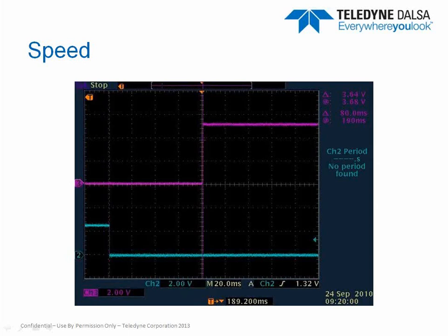And it was really constant. If you see the number below, it was around 189 milliseconds. So again, some of the vision software tells you the processing time, the acquisition time, but if you scope from trigger to output, you get the real true time for it. So do tests, especially again, in really, really tight critical applications.